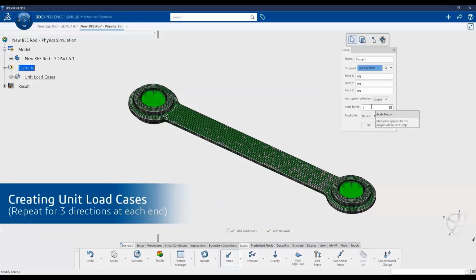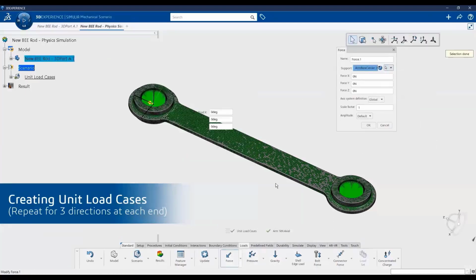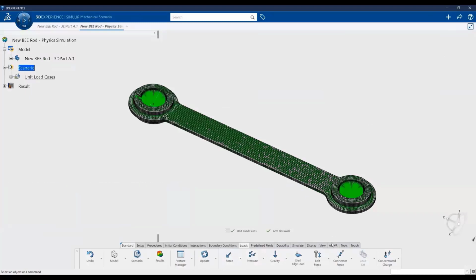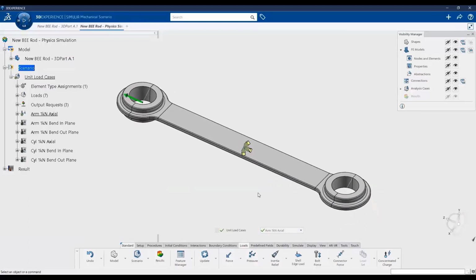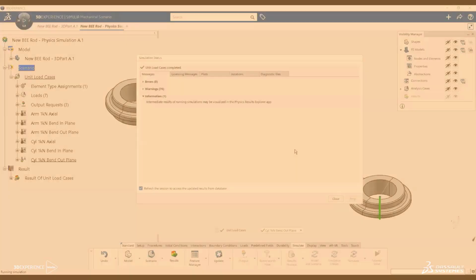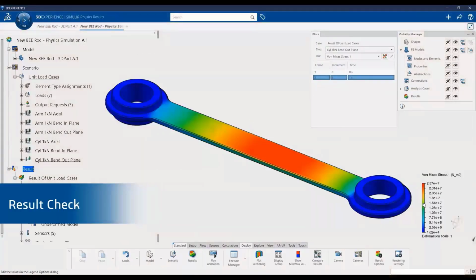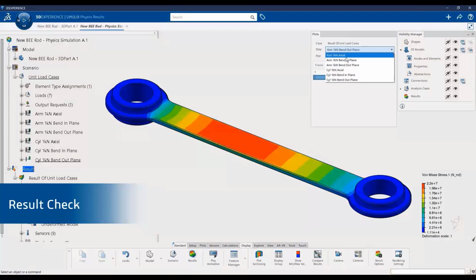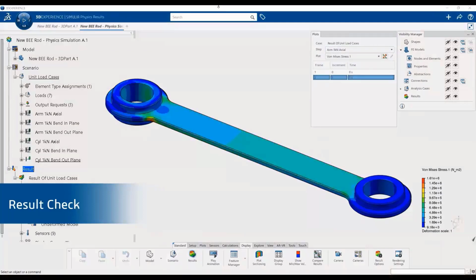So after doing the mesh, we are applying some loads. And here what we'll do is apply a lot of different loads, and we'll solve each load in what we call a different step. You can see here we created different steps with different rod orientations, and we will solve all of these loads. So these are different types of loads that the rod can have in its life. So now what we do is run the simulation. By the way, we run the simulation on the cloud. We can run it locally or on the cloud. This is integrated on the cloud, in the tool.